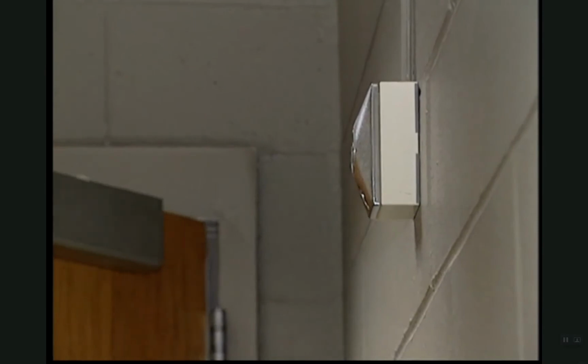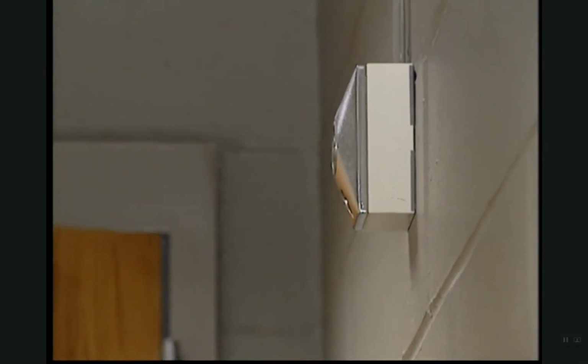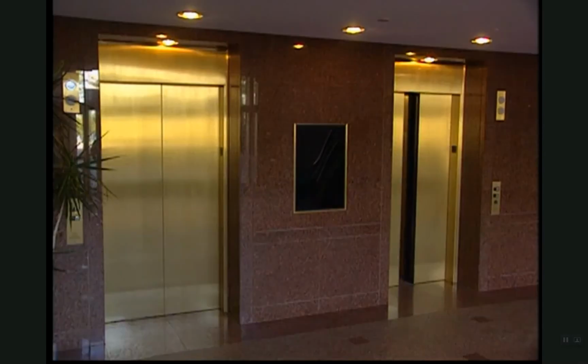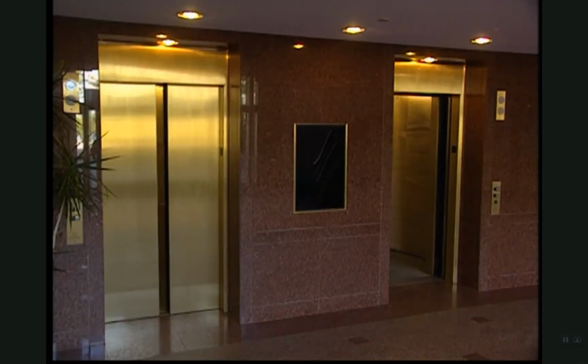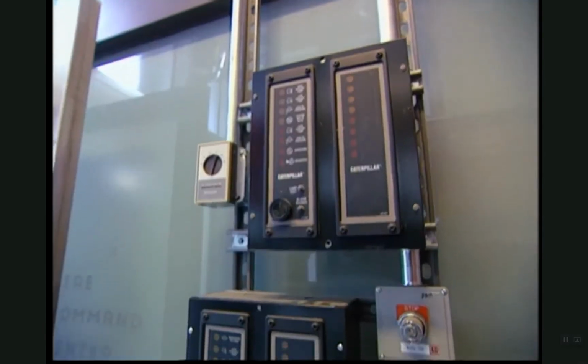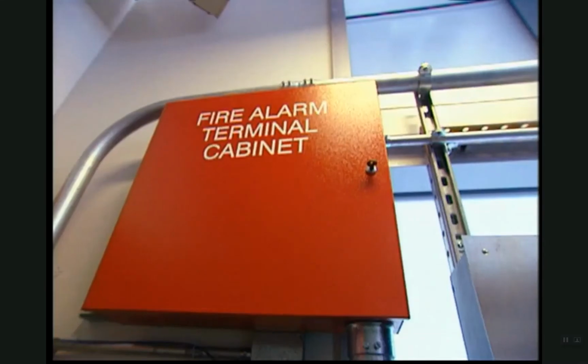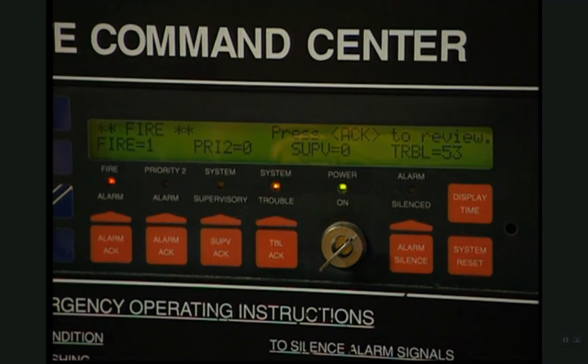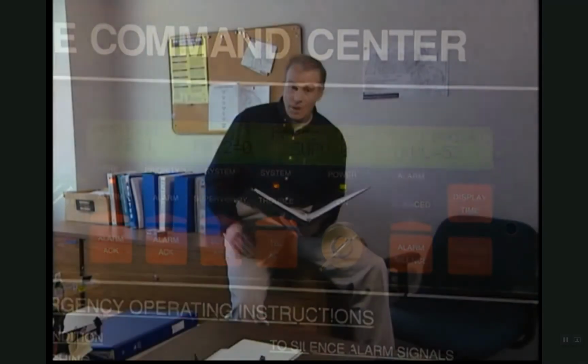When a smoke detector has a control output function in addition to its alarm output, for example, operating duct dampers, shutting down power, or recalling elevators, test to verify that the control output works, even when all other devices installed on the same circuit are in an alarm condition.